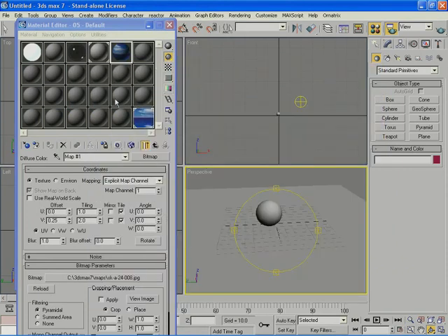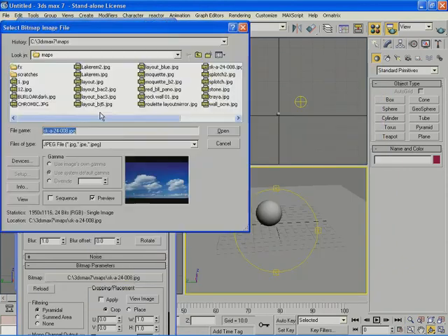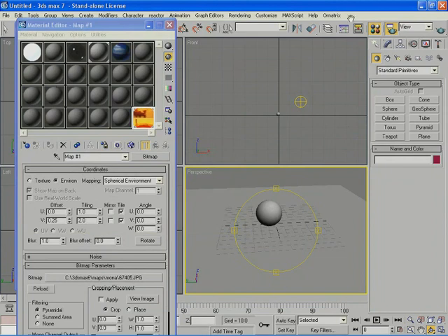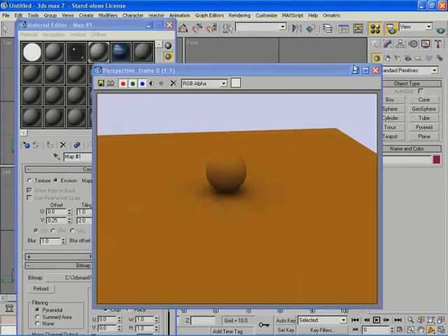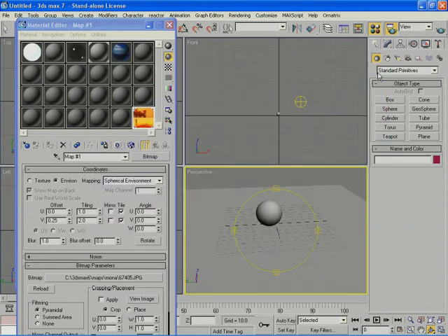Now these are regular textures. Normally we use something extra. We use something called an HDRI map, which we'll talk about in coming examples. So for now, I'm not going to use any map. So I'm going to regain my skylight and uncheck map. And for now, I'm just going to use the sky color.